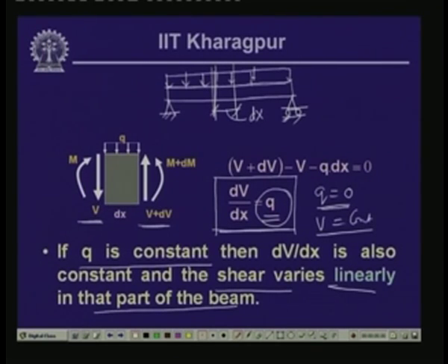In fact, if you remember, for a simply supported beam, if q is the uniformly distributed load, and since we do not have any horizontal force, the reactive force we will have at this hinge support is a vertical one. If we call this A and this B, then this is R_A and this is again a vertical support, R_B. This being symmetrical, we can write that R_A is equal to R_B, which is equal to qL over 2, where qL is the total load. So, half the load will be carried by reactive force A and half by reactive force B.